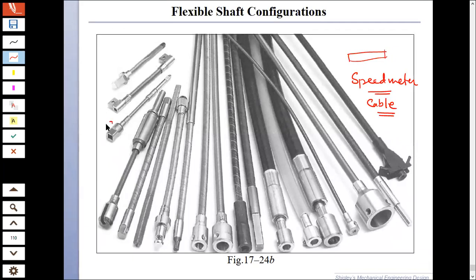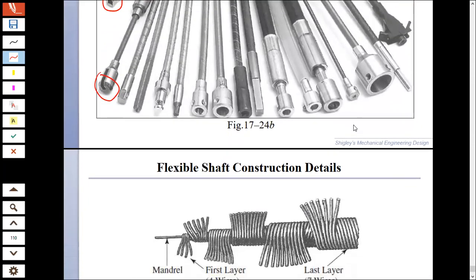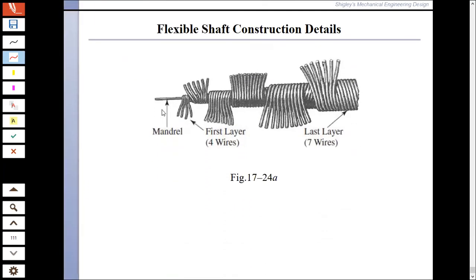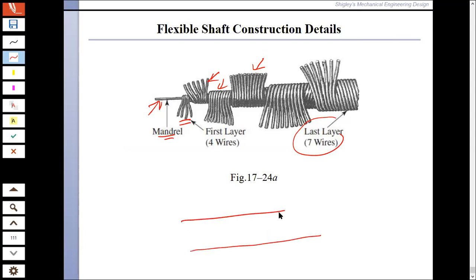And if you look at it, its heads are made in different forms. If you look at a flexible shaft, this is how it is made. There is a mandrel, it's almost like a rope. This is the mandrel. Then there is one layer of wires, then another layer of wires over that, another layer over that, and then there are many layers. What you do is take this and put it inside a kind of tube. Now, when you rotate it from this side...